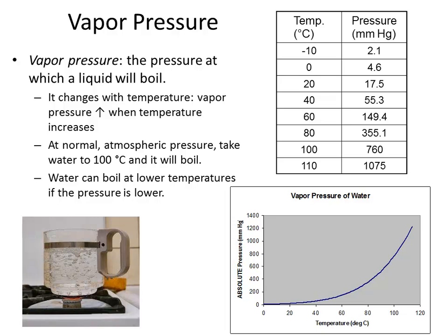And remember that when water is being sucked from a reservoir up into a pump, the pressure is always decreasing in the direction of flow. And so the risk that we're facing when we are moving water from the suction side of the hose into the pump is that the pressure will get too negative, that in gauge terms it's negative.